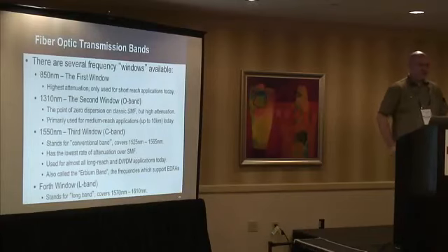The next one was the 1310 window. And it was the point of zero dispersion on classic single mode fiber. But it has pretty high attenuation. So today we typically use that for medium reach stuff.